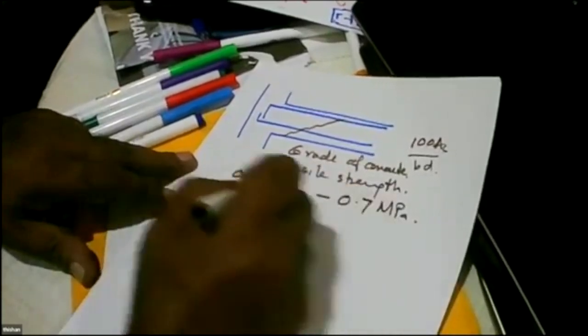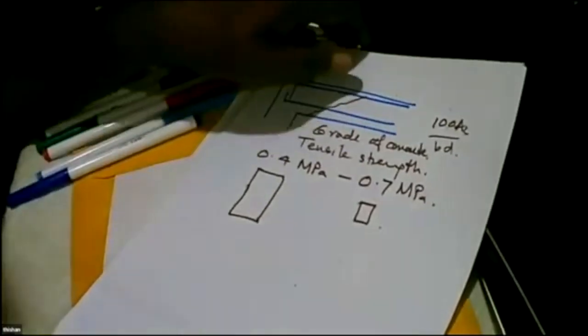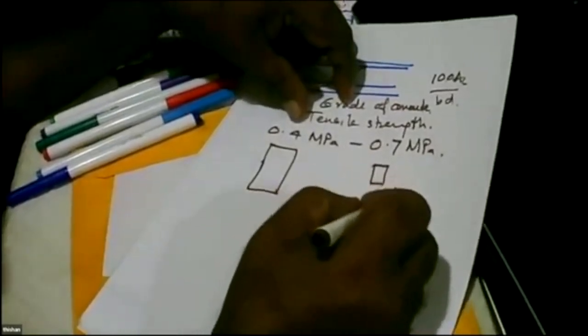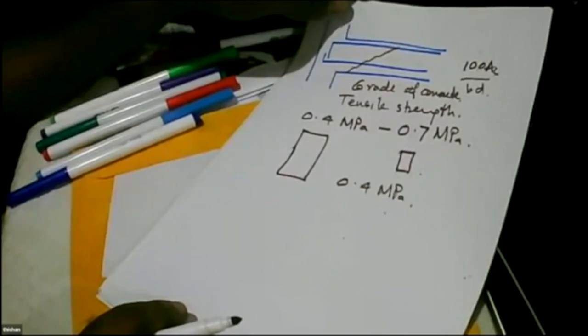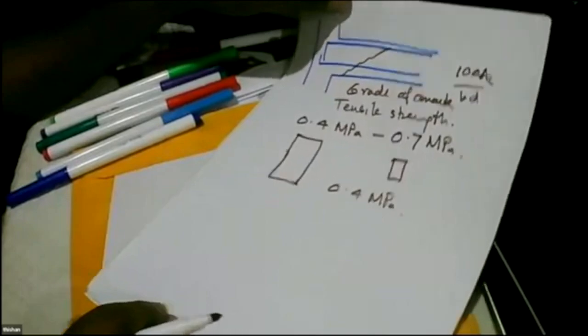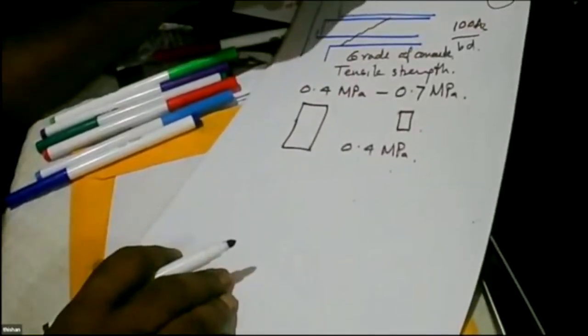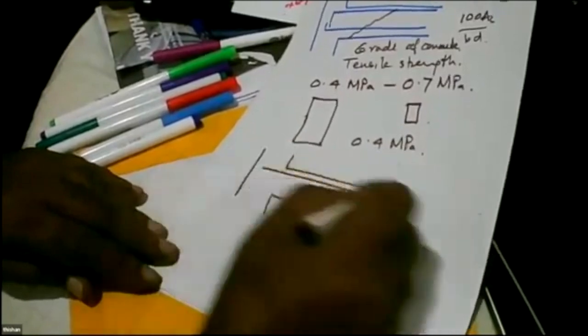So, bigger the section, this side; small section, this side. Bigger the depth, close to 0.4. So for most of my calculations, I don't bother to check the value. I simply use it as 0.4, because the variation is so small to get any advantage, so I just use a value of 0.4, 0.45. Not more than that. Most of the time you check the code and finally find 0.4 to 0.45 is the value that you get after calculation. So I just generally use 0.4.